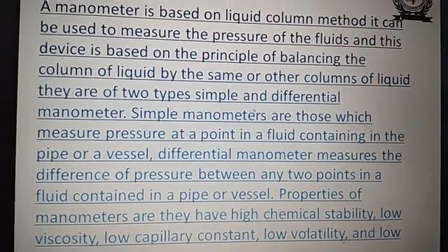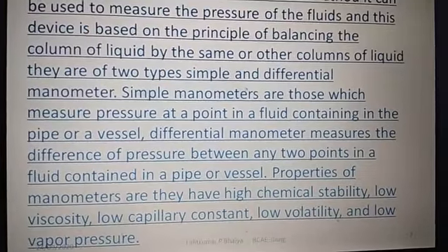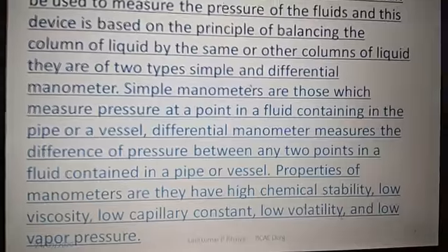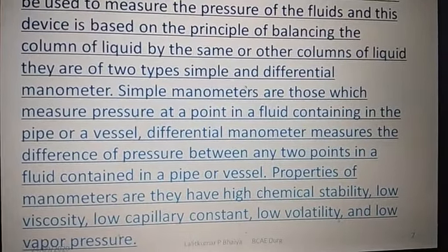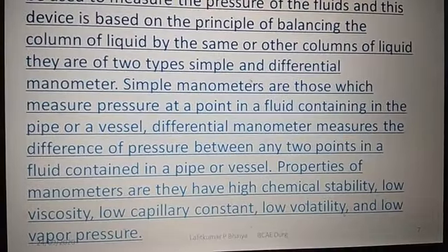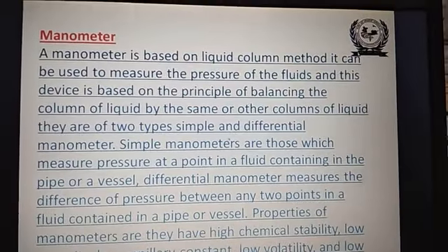The properties of manometer liquids are high chemical stability, low viscosity, low capillary constant, low volatility, and low vapor pressure.